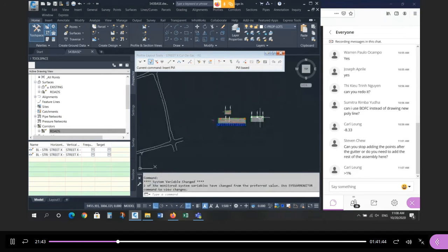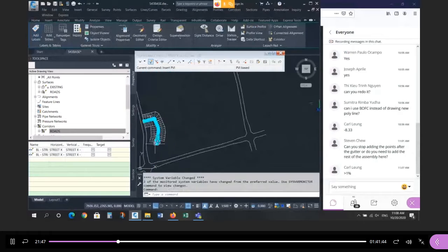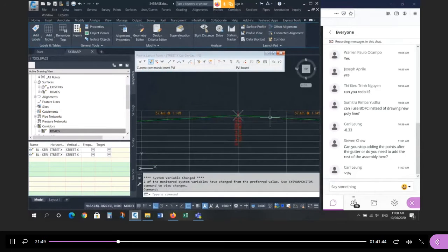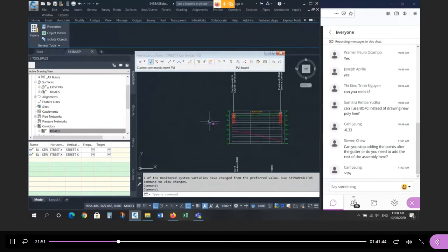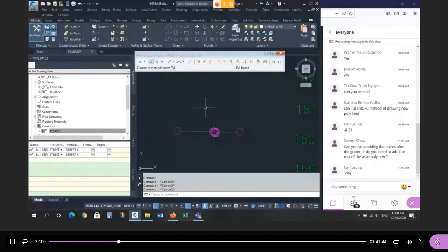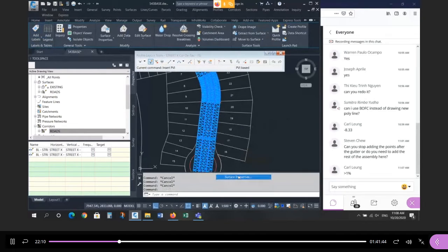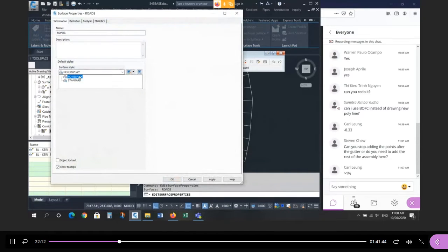So now I have, just like any other corridor, a horizontal alignment, a vertical alignment, and a cross section. The same one. I want to drag this all the way around. So now I have plan, profile, cross-section, the 3 basic building blocks of a corridor. I'm not going to create a separate corridor. I'm going to add to the current corridor, and I'll have one model that shows all this. Okay. Let me turn off the surface for just a second. Surface. Turn off the view.